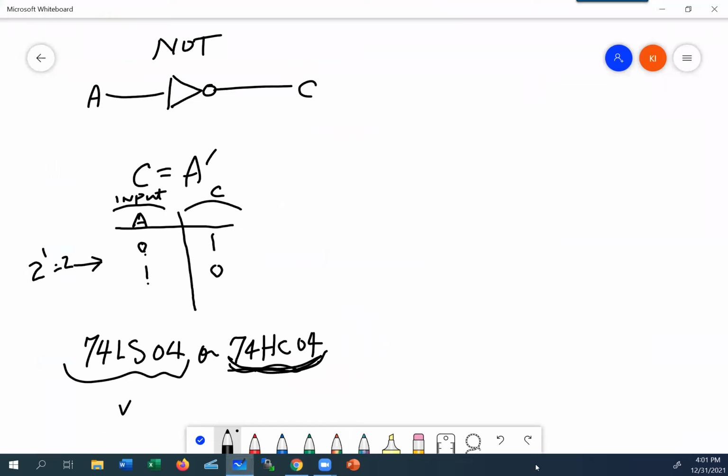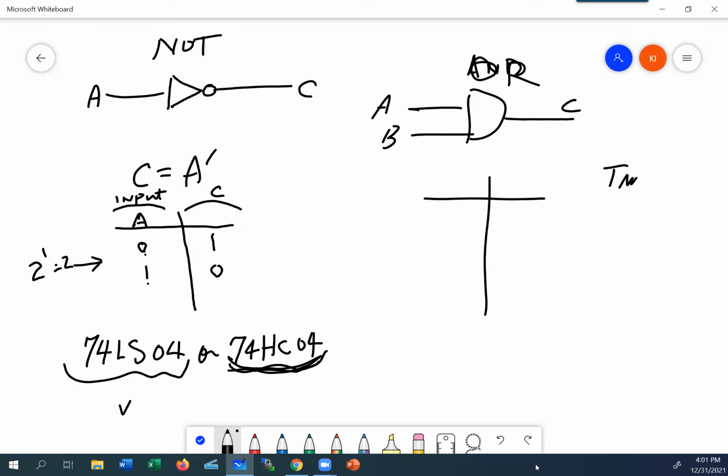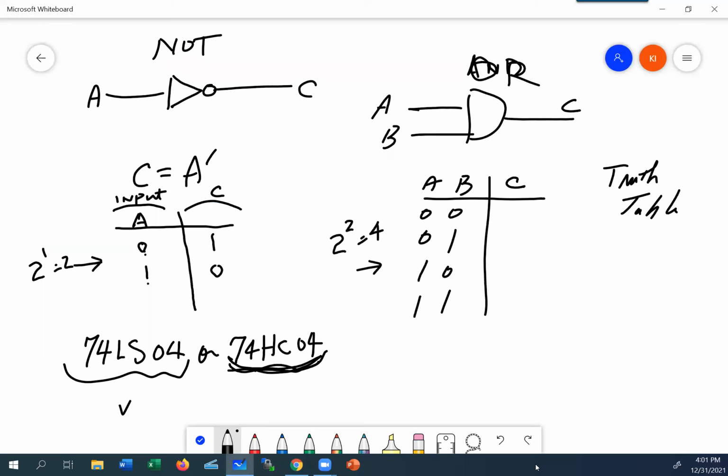Let me go ahead and write this so we have looked at this as well. I'm sorry, it was OR, I think, that was the last one. OR is the last, and we already did it. For OR, A and B are the inputs, C is the output. This is the truth table. You always need a truth table to make sure you know how it operates. Inputs are A and B, and the output on the other side is C. We write everything in order: binary 0, 1, 2, 3, and that's all the possibilities we have with 2 inputs. If you have 2 inputs, you have 4 possibilities, and we have captured that. The way we write it is that C is equal to A OR, which is a plus sign, B. So 0 OR 0, if they're both 0, the answer is 0. If any of them is a 1, you get a 1.